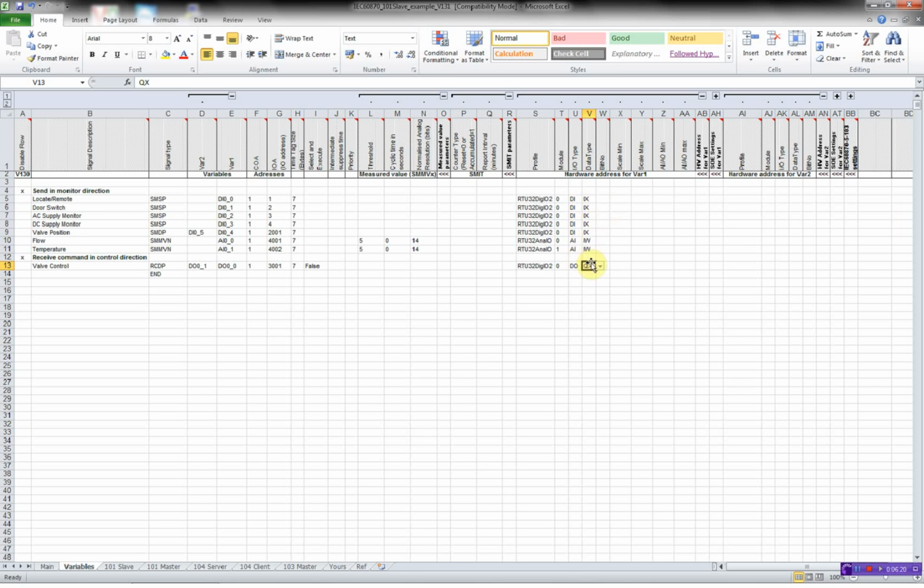Now this is done, then we'll define the bit numbers 0, 1, 2, 3, and 4. This is actually a double point, so it's using two IOs. I can choose whether to define the second IO, but otherwise the generator will automatically select the next bit number.